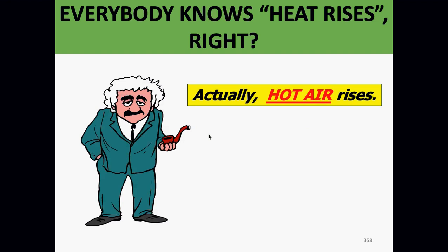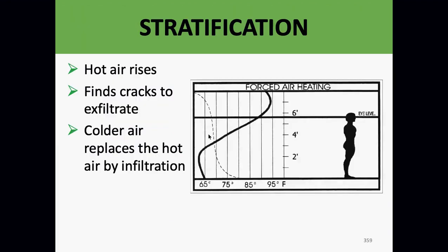You keep hearing people say heat rises. Well, actually hot air rises. It's lighter. It's called stratification. We've talked about this. Hot air rises, it finds cracks. So again, when you look at your houses, I saw a couple pictures of some areas in some people's houses, when you did that identification of things that could cause air quality problems, a couple people had whole house ceiling fans. Got to seal them when they're not being used. And I know the pictures I saw, they were sealed. But just want to point it out, got to seal them when they're not being used, because it's going to find cracks in any place to exfiltrate.